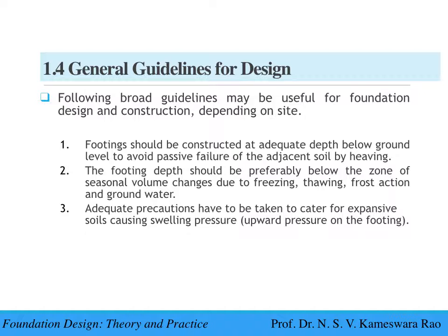1. Footings should be constructed at adequate depth below ground level to avoid passive failure of the adjacent soil by heaving. 2. The footing depth should be preferably below the zone of seasonal volume changes due to freezing, thawing, frost action and groundwater, and so on. 3. Adequate precautions have to be taken to cater for expansive soils causing swelling pressure, upward pressure on the footing.